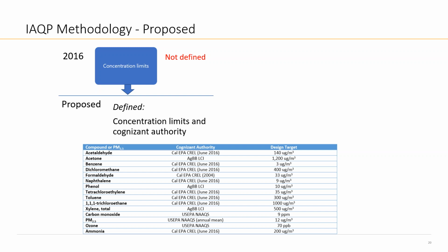I just want to caution, and I have heard this conversation in ASHRAE multiple times: you cannot design a space and say that 5,000 parts per million of CO2 is okay for our kids in schools because OSHA said so. On ASHRAE's position, you can correspond further with the ASHRAE chair of 62.1.